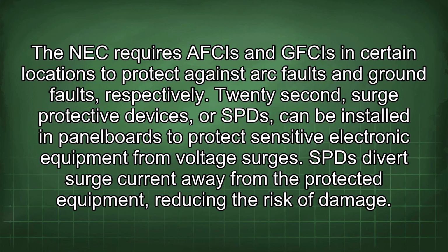22nd, surge protective devices, or SPDs, can be installed in panel boards to protect sensitive electronic equipment from voltage surges. An SPD diverts surge current away from the protected equipment, reducing the risk of damage.